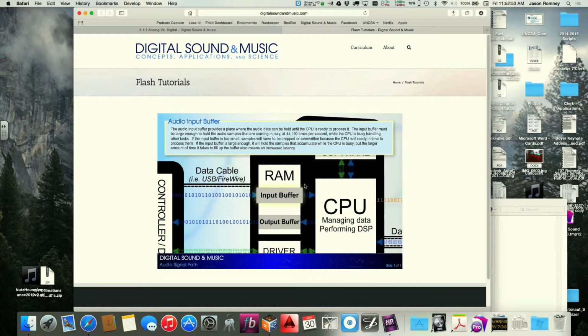So this is something you've got to keep an eye on. Every digital audio system is going to have some sort of input buffering. Sometimes you can control it, sometimes you can't. Like in a digital mixing console, you usually can't control the buffer. But you know what you can control? The sampling rate that mixing console runs at. So the buffer may not change, but the sampling rate can. And a higher sampling rate is going to get through the buffer faster. So there's one plug for why you might want to run at a higher sampling rate on your mixing console, because you could reduce the latency that way. Since you can't manipulate the buffer, that's just one idea. Unless they're being sneaky and changing the buffer when you change the sampling rate, which would be really annoying. Some of them do that.